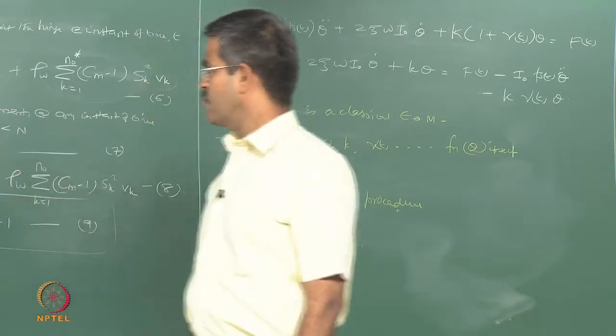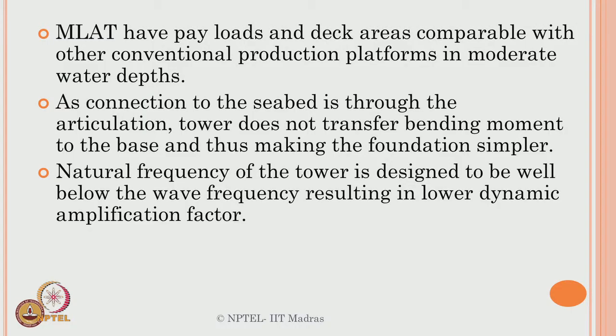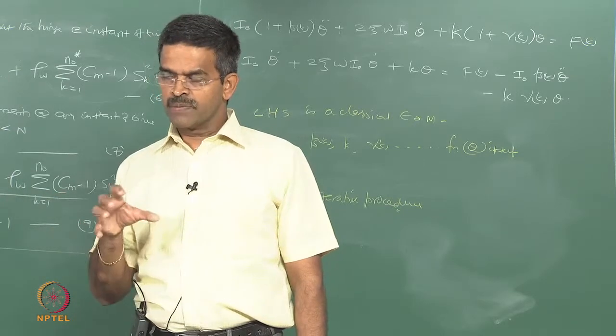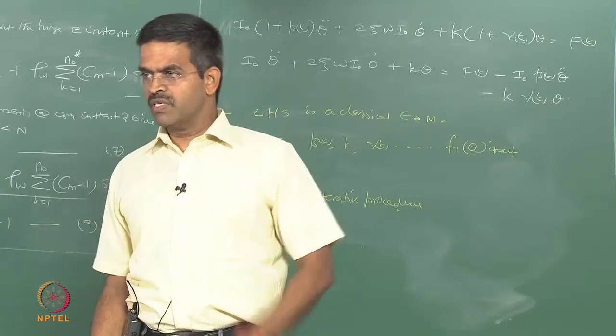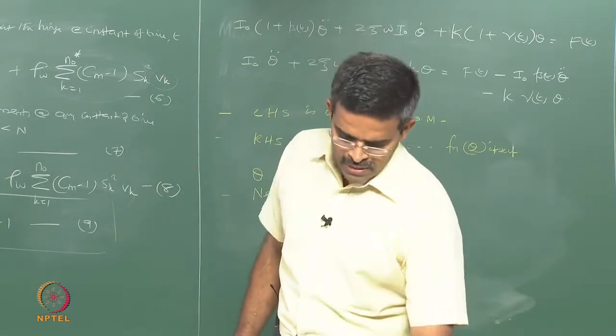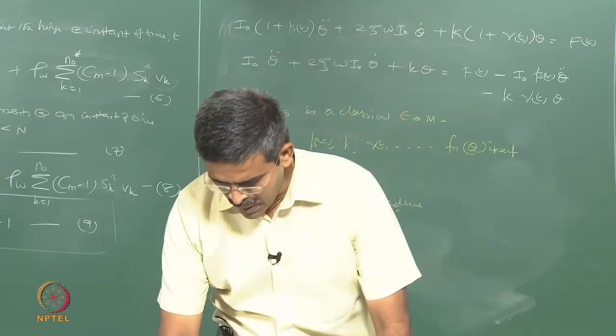That is one advantage. And more interestingly, the natural frequency of this platform has been studied in such a way that they behave much lower than the dynamic amplification factor. Okay, they do not amplify the effect, that has been studied. I will show you some results later. So some of these merits have been understood while people conceptualized multi-leg towers vis-a-vis single leg towers. Okay, that is how the dynamic analysis progressively happened from single tower to multi-leg towers.